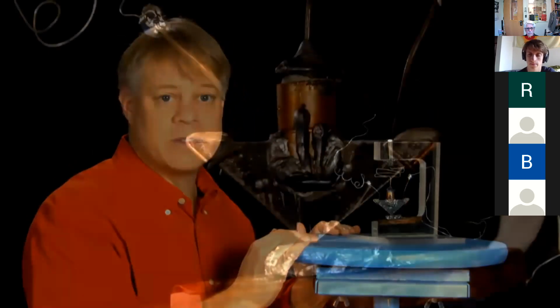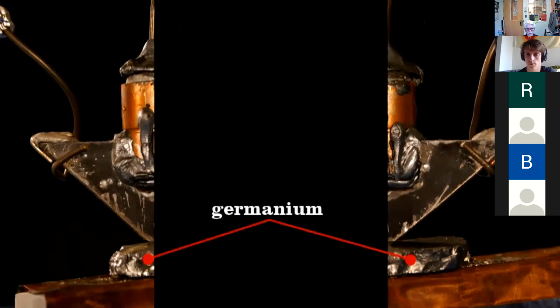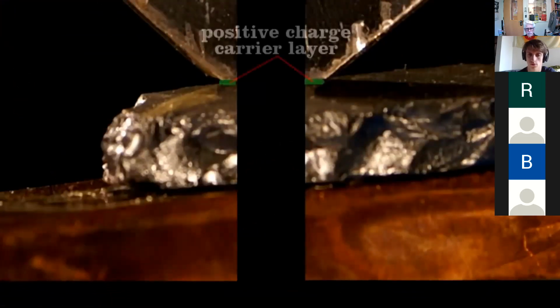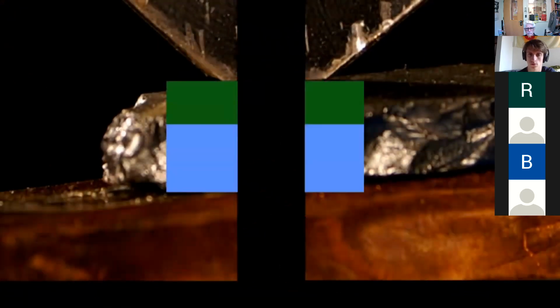This seems a simple thing, yet it lies at the heart of a microelectronics revolution. And it's the key to the Brattain and Bardeen transistor, in fact to every transistor. It's best to first think of their device as two separate one-way current valves. At the center of each is that piece of germanium, which makes electrical contact. And at the top, a spring presses a thin piece of gold foil into the germanium. Right where the gold touches, there's a thin layer of the positive charge carrier semiconductor. Below that, the rest of the germanium is the negative carrier type. Now, even though that top layer is very thin, I've exaggerated it here to make the operation of the transistor clear.